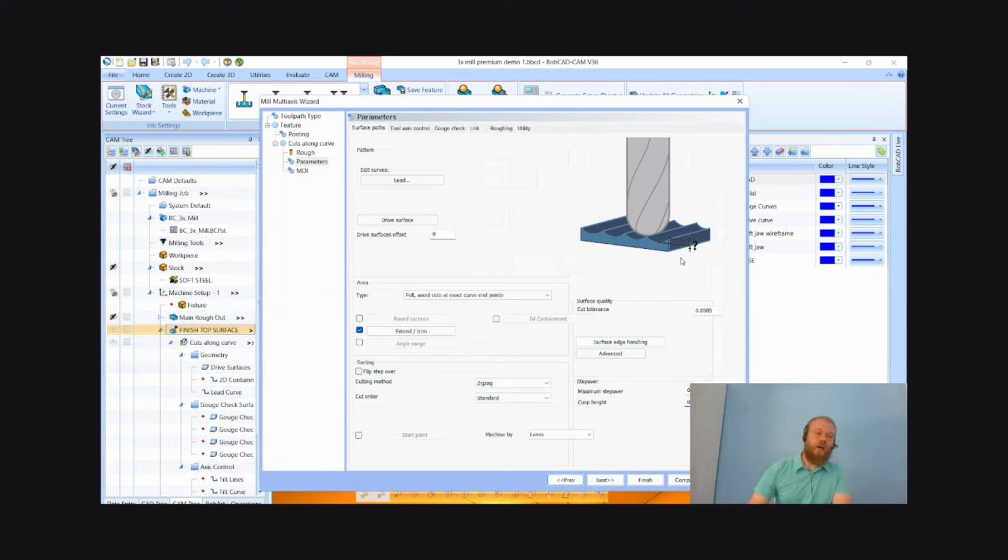So I don't have to go into simulation and guess and check the surfaces and the tolerance level. It will have the tolerance level set up with that step over calculated right there. Those two numbers are related to each other. Set 1/10 there for my cusp height, and it'll automatically set up 12 thou for a step over.